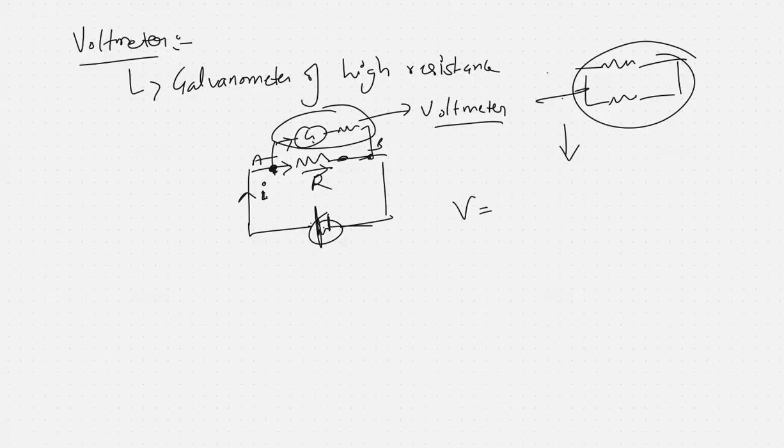Potential is V. Now this voltage should be equal to whatever current Ig is passing multiplied by Rg plus Rs, this shunt resistance. This is what the current is about. If you see carefully, let's rewrite the equation. V by Ig is equal to Rg plus Rs.